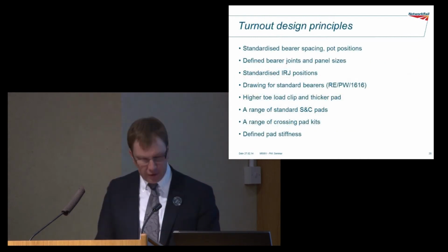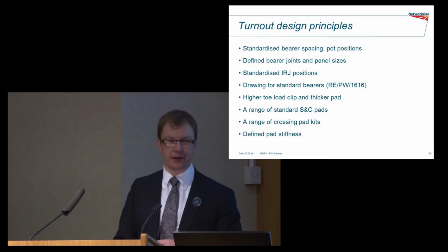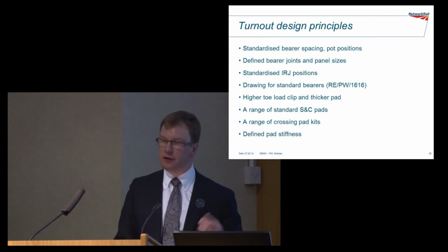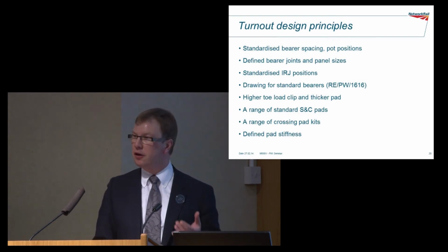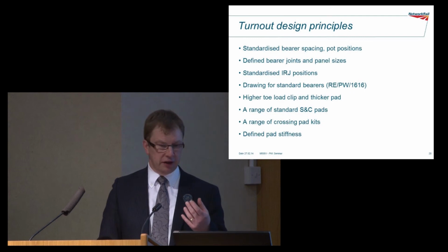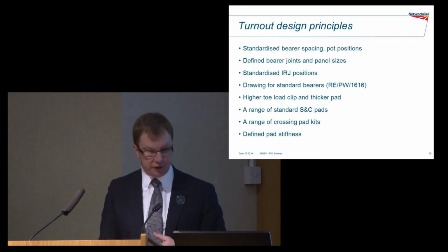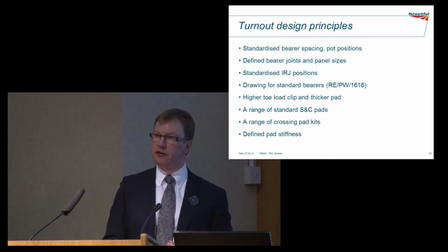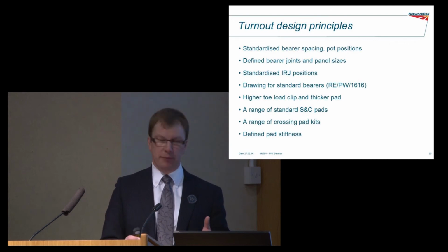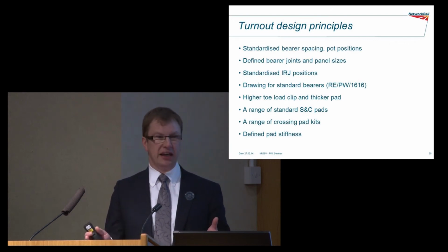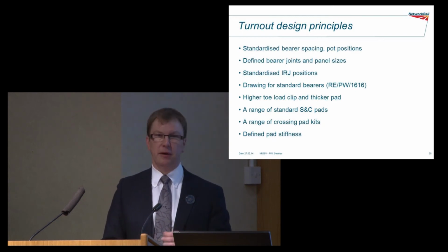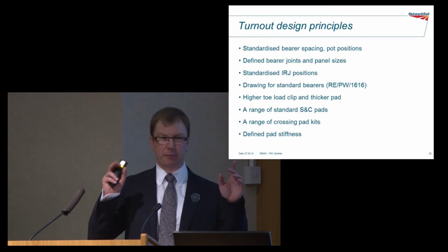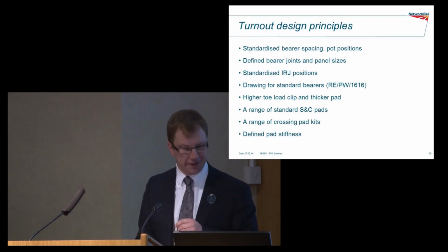So really there's a load of stuff there. I think I've already said all that actually. It was just really a summary, and for anyone looking at the presentation later. The pads, they're all shown on drawings as well. So we've got one drawing that shows all the standard pads, but there are a range of standard pads, and then there's a separate drawing that shows the crossing pads, and the crossing pads are designed to be ordered in kits. So for a particular crossing angle you can order a kit of pads, and they've all been given a pads number for pads, which is always confusing when I get into talking about that.